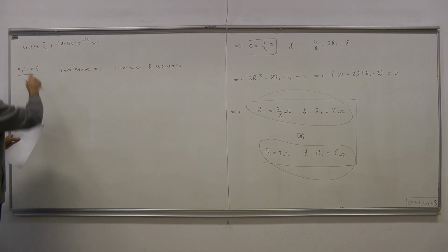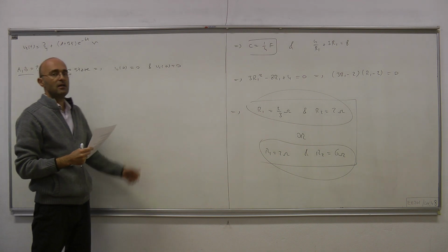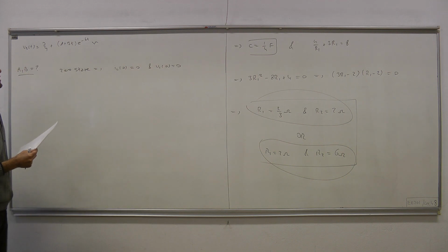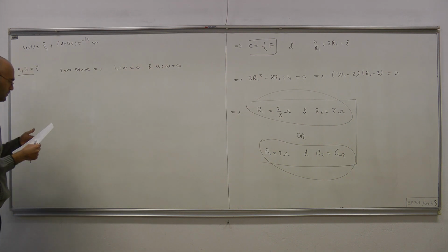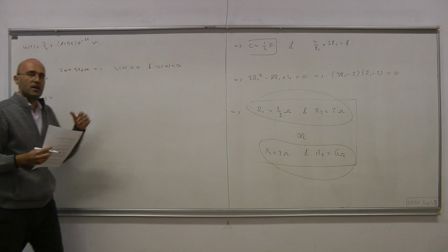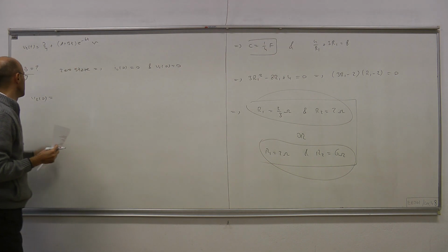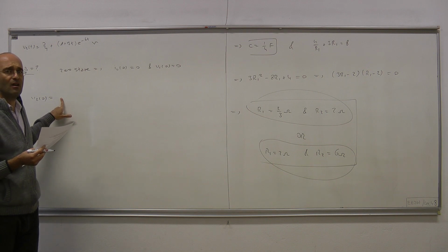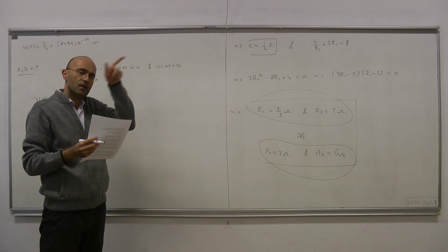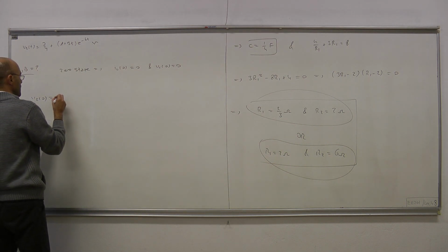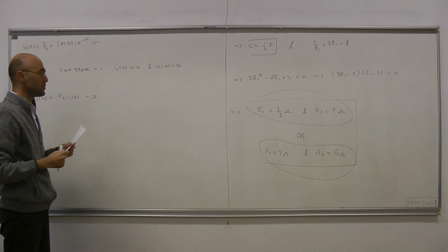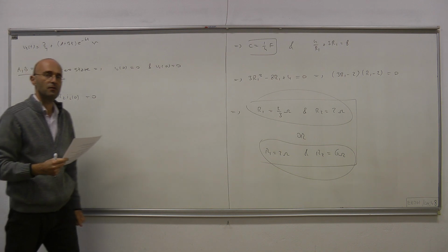Okay. Now, the solution is in terms of neither IL nor VC, so we have to transform this information into the initial condition information for V2(t). Okay. So what's V2(0)? V2 was the voltage of the second resistor, and therefore it's R2 times the current of the second resistor, and the current of the second resistor is the same as the inductor current because they're in series connection. So this is R2 times IL(0). Since initial inductor current is 0, that means initial voltage for the second resistor must be 0.